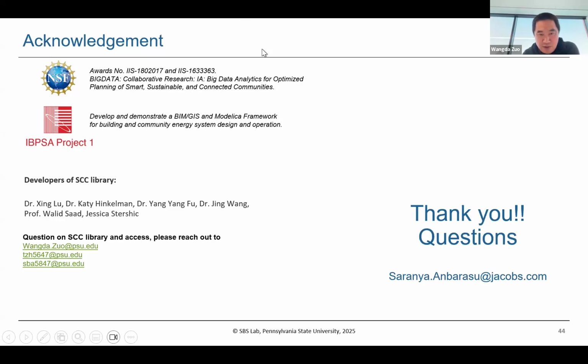Okay, we have questions. Saranya, you can read the question. How did you implement the quasi-random sampling in Modelica? So quasi-random sampling was implemented in Python first, and we generated samples, and then those were converted into input files with different data sets, and then passed into Modelica to do multi-simulations. Did you use FMU or you just use BuildingsPy? It was through BuildingsPy for this work.